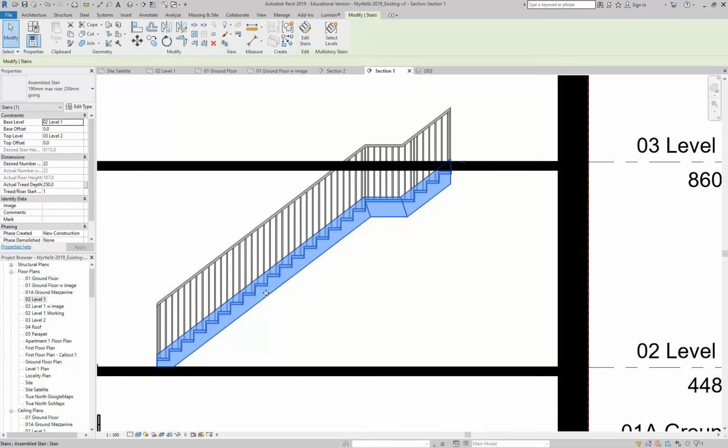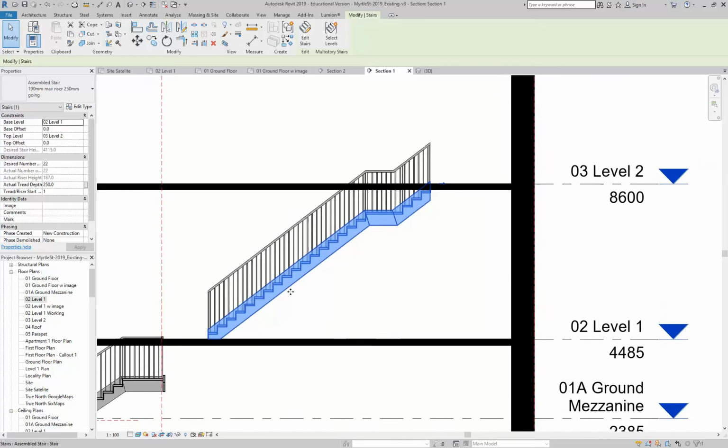It's supported from the wall, and they've got all sorts of framing that will go into the wall. Well, these days they just bolt in, and they've got these U-shaped brackets, essentially, that the stair then gets mounted on. And they're steel, so they're strong, and they can cantilever out from the wall. You need a bit of depth in your wall though. And there's some really good examples all around town, you'll see of those.